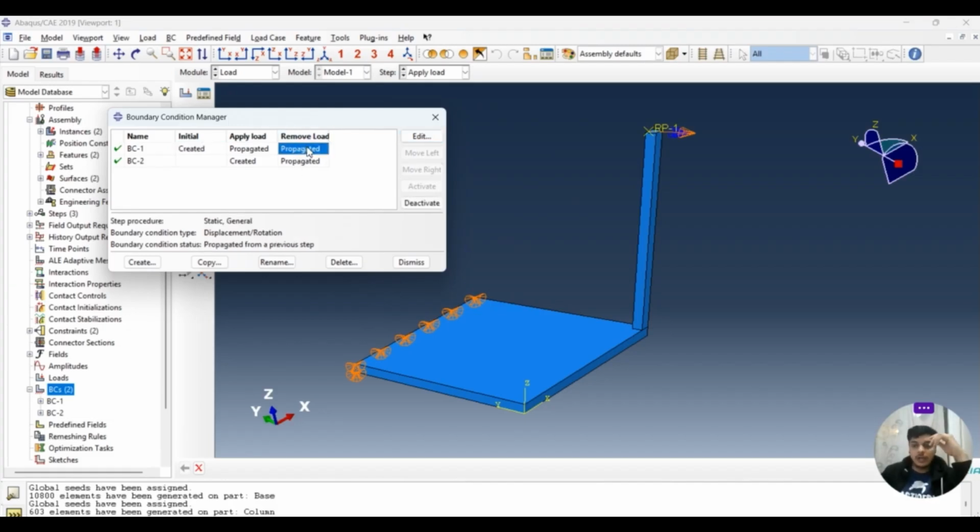Also, we don't want to bring it back, correct? We don't want to apply any load to bring it back, because then it becomes not a plastic problem, but you just force it back to the original position. But we want the plastic nature. So we have to deactivate this, which means when we remove the load, it will come back on its own as per the material properties.